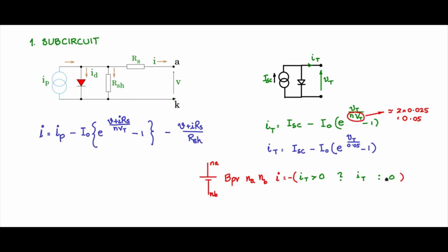model. Next comes the point on how to adjust the voltage of the PV module. Can I increase the voltage of the PV module? Now let us say here in this point of the equation, I divide by a V scale value. Now let us say, for example, when V scale was not there, VT terminal voltage was around 0.7 to 0.8. Now if I make V scale a value 10,